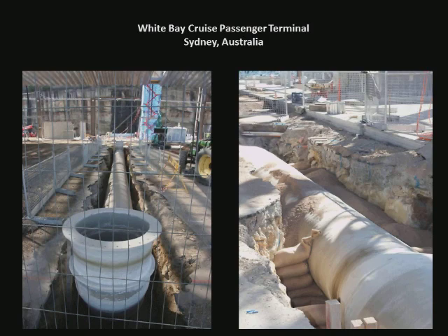So again, with a terminal or a train terminal, airport terminal, we're not concerned with cooling the whole 20-foot vaulted ceiling we might have. And people may not even realize that there's an air conditioning system at work. Certainly you would notice that it's much cooler inside than outside, but by hiding the register grills underneath people's seats and having slower, warmer air movement, you're not going to have that draft effect that makes it quite as obvious.